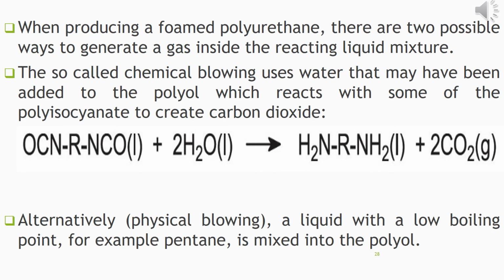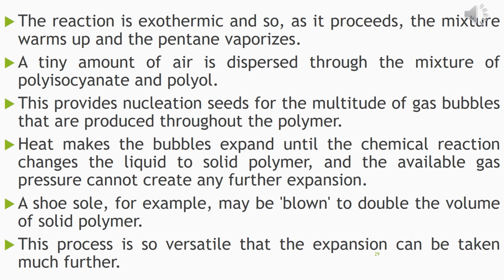Alternatively, in physical blowing, a liquid with a low boiling point, for example pentane, is mixed into the polyol. This reaction is exothermic, and so as it proceeds, the mixture warms up and the pentane vaporizes. A tiny amount of air is dispersed through the mixture of polyisocyanate and polyol.